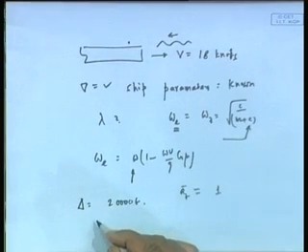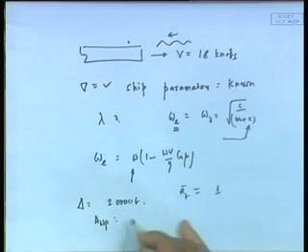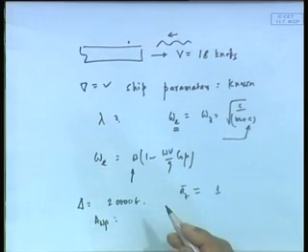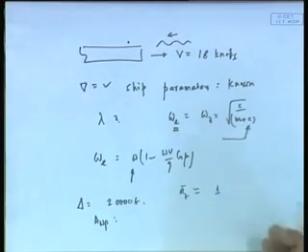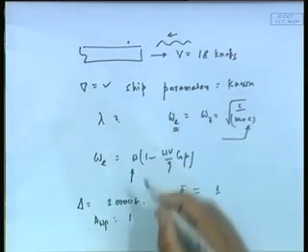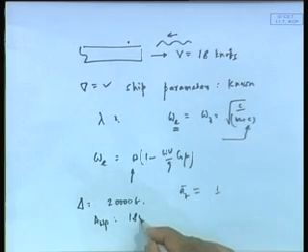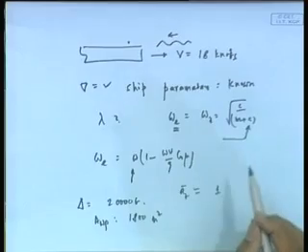Water plane area, I need AWP. Well, actually sometimes what will happen is that we will give L and B and then CWP, etc. Say AWP is also given. It can be maybe 1800 meter square or something like that. Find out the lambda for 18 knots.